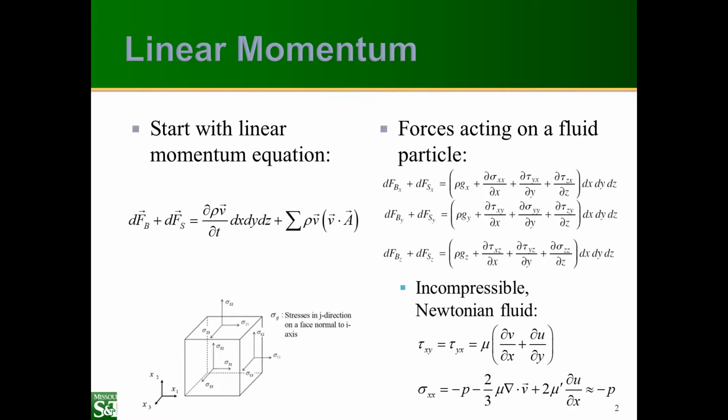Now, we talked about incompressible flows during our discussion on the continuity equation, and in that case, del dot V is equal to 0, so this term right here is equal to 0. So if the flow is incompressible, this term is going to be 0 always. This term is the bulk viscosity, which is basically compressibility effects. It measures the transfer of energy from velocity to other modes like rotation and vibration.